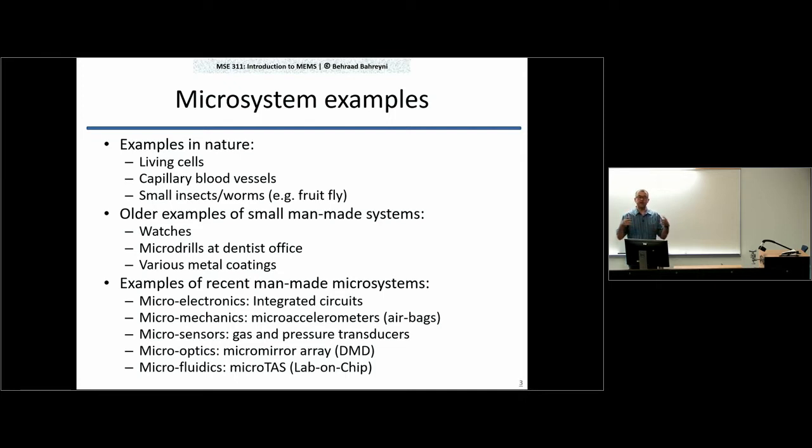But because we're making 1,000 of these devices at once, or 10,000 of them at once, the cost is distributed among those many units. So if a silicon wafer costs me $5,000 to finish, from the beginning to finish, but it has 10,000 devices on it, the cost per device at the end of the story is 50 cents. And this batch fabrication has made 2 things possible. Firstly, I will have a lot of these devices. I can make hundreds, thousands, millions of them. And secondly, the cost is low. The cost per device is low. So it's systems that will need these components now. You can design systems that utilize these components, and then they are not going to break the bank.